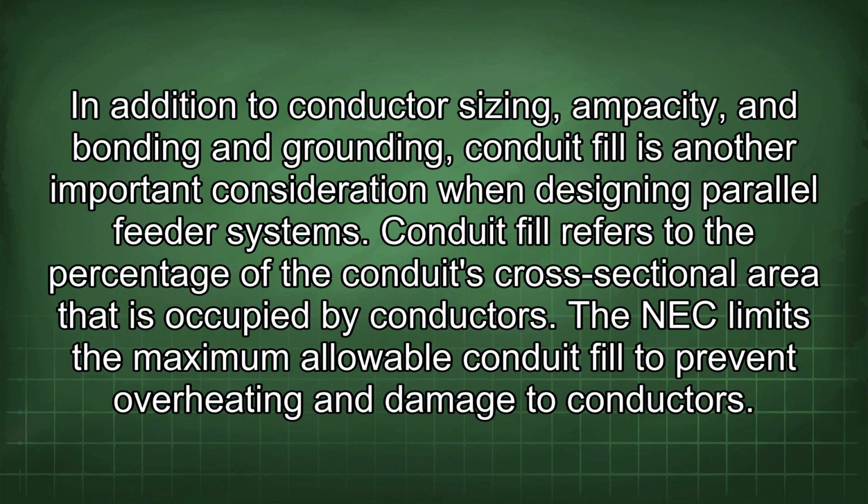In addition to conductor sizing, ampacity, and bonding and grounding, conduit fill is another important consideration when designing parallel feeder systems. Conduit fill refers to the percentage of the conduit's cross-sectional area that is occupied by conductors. The NEC limits the maximum allowable conduit fill to prevent overheating and damage to conductors.